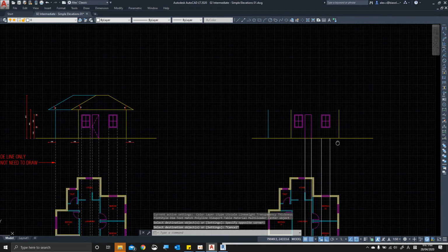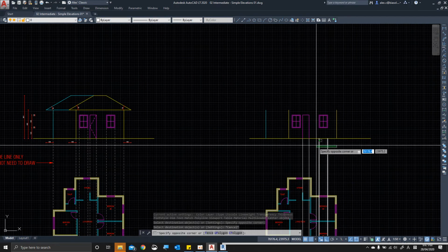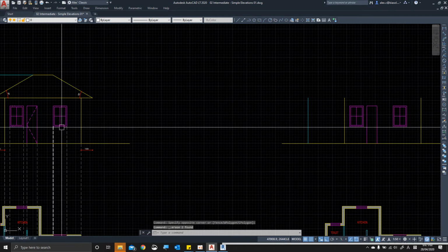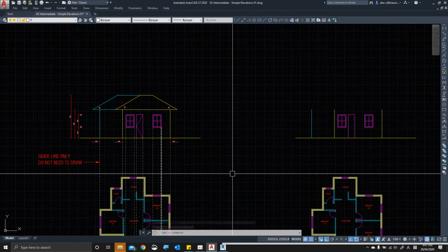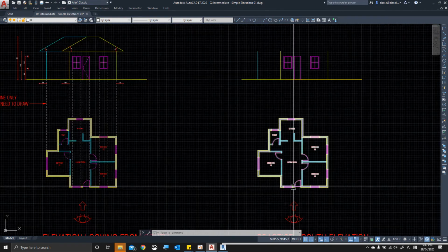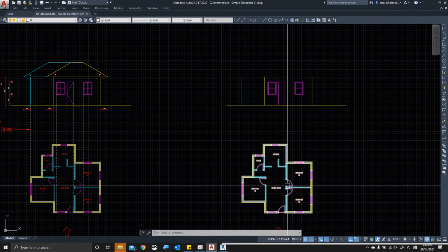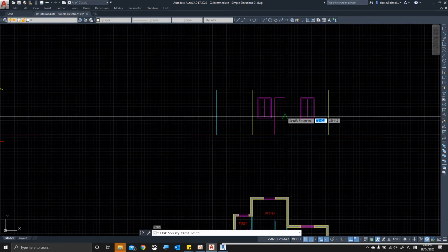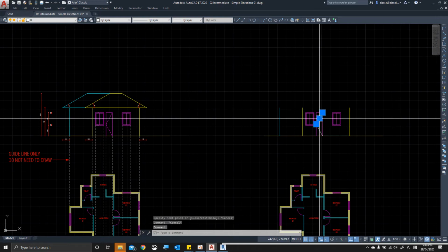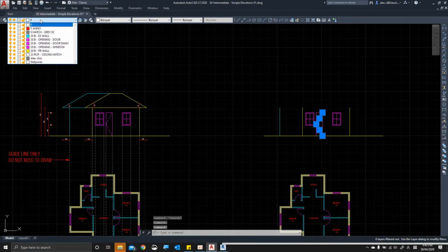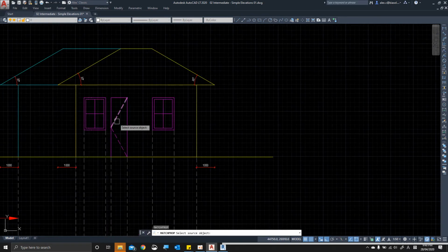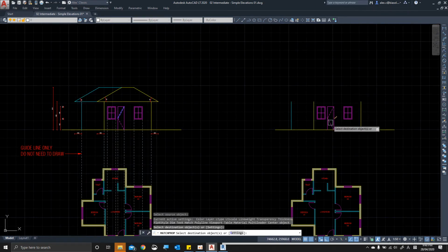Because we already finished drawing the window, I'm going to get rid of those two. It's almost done. You also need to show where the handle is, so check which direction the door is opening. That way, so the handle would be on that side. Basically, that is that. To make the dash, I know you need to select the appropriate layers from there, but only for this exercise, just match property there.